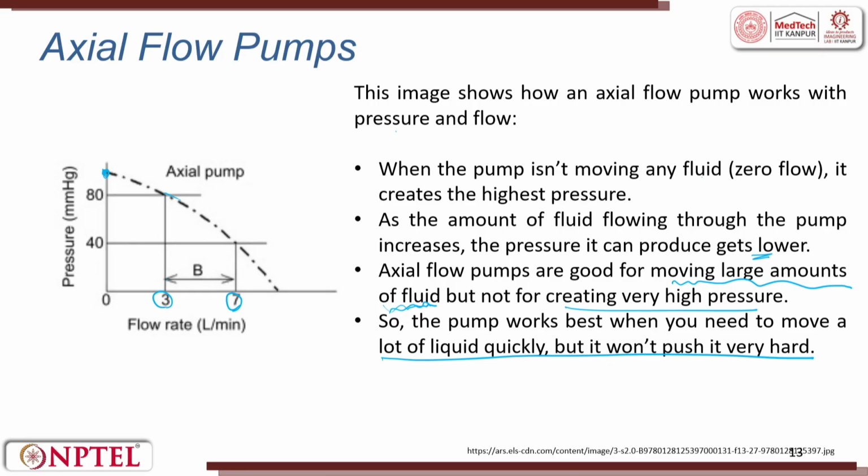When there is a flooding situation and water has to be moved out of the existing space to a nearby space, from a road to a sewage tank, then we try to use these axial flow pumps. Here it will move liquid very fast, but it will not be very hard. The pressures will not be very high. That is what we wanted to say.